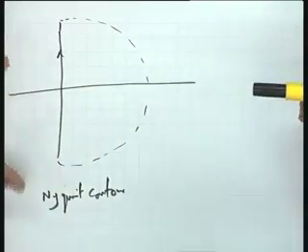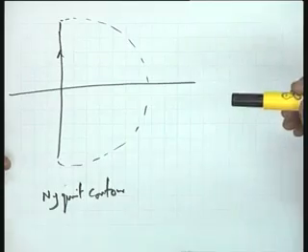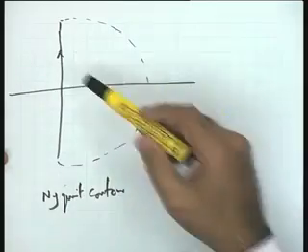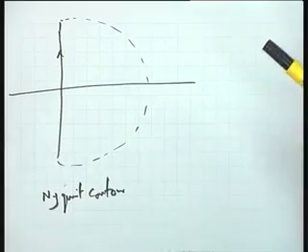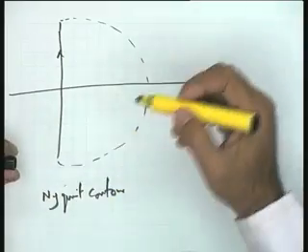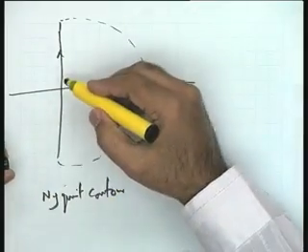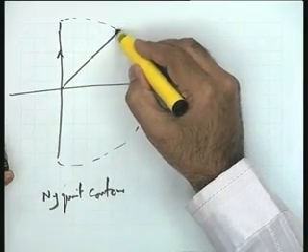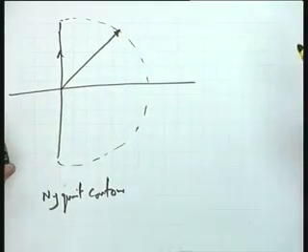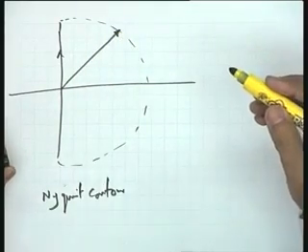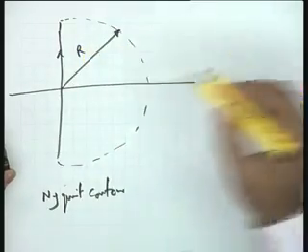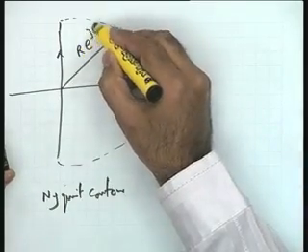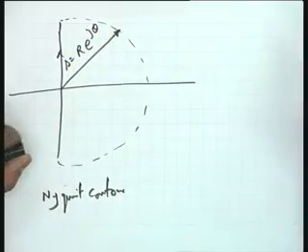in the region enclosed by this particular contour or not, which consists of the imaginary axis as well as the entire right half plane. When I go for mathematical mapping, this particular contour will be mathematically modeled as a circle of infinite radius. So r is the radius and r e to the power of j theta becomes the value of s.